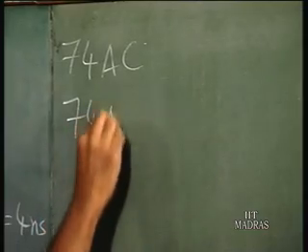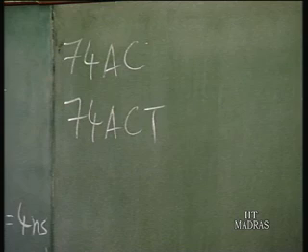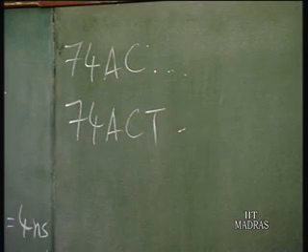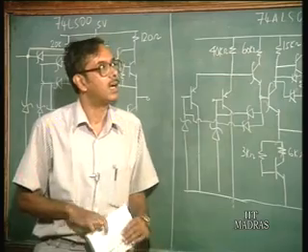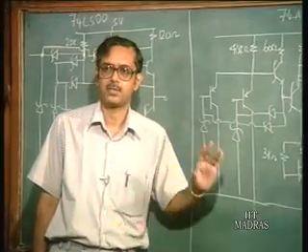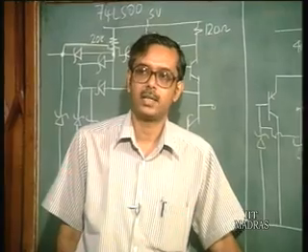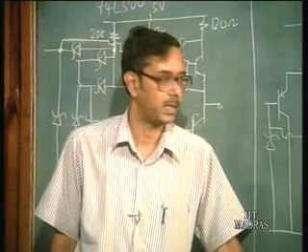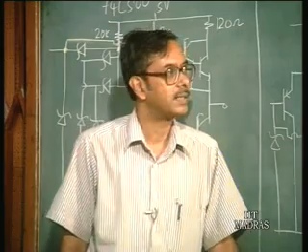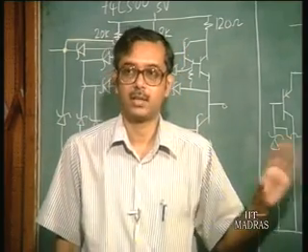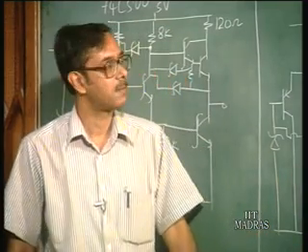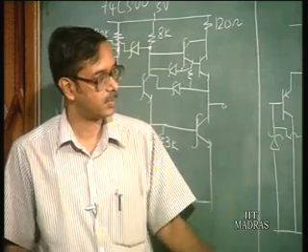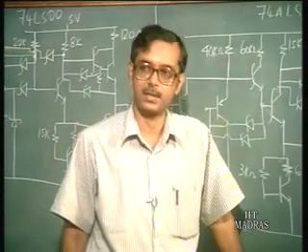So these are basically CMOS families, but they have pin compatibility with the 74 series as well as input output compatibility. There the delays are about 5 nanoseconds or so, but the advantage of CMOS is very low power dissipation, even much lower than this. So that is another advancement which has taken place. Of course they are not the exact TTL family, but that is also available, and a lot of further advancements have gone in that direction.